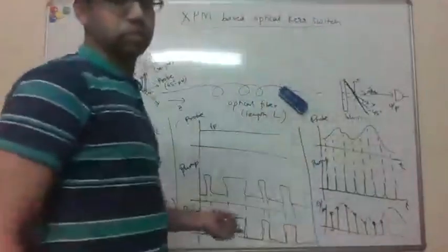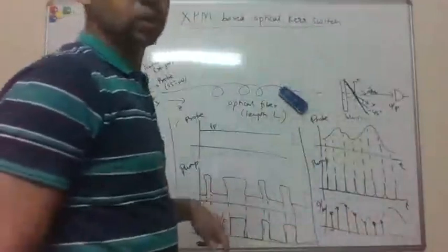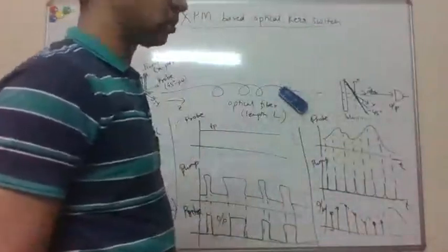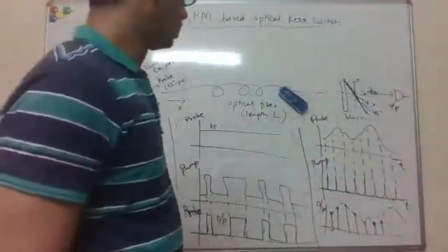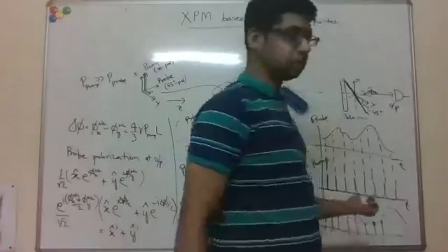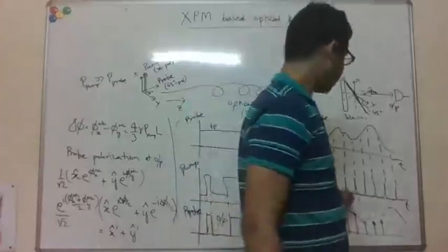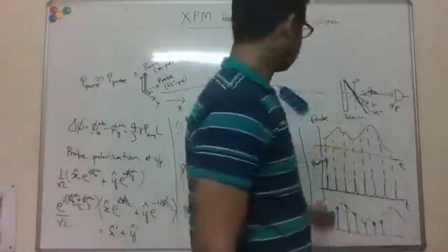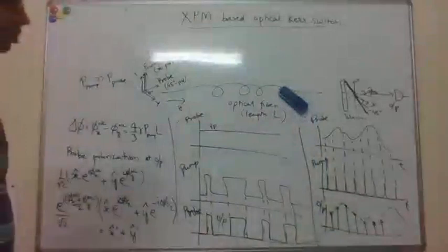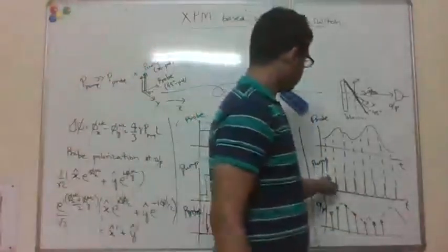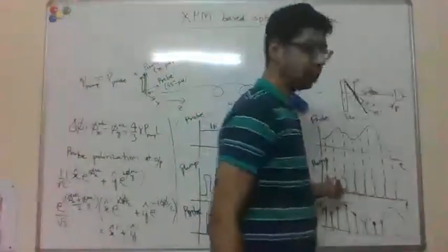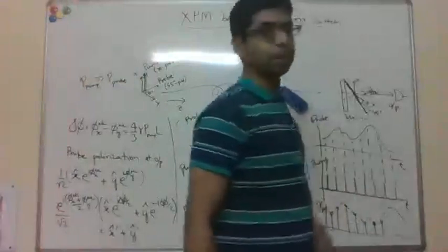And in the optical domain, the speeds can be much faster, right? In electronic sampling, you are restricted to 2 gigahertz rates. That's sort of the state of the art. But here you can get mode-locked lasers. Nowadays, people can make lasers which have repetition rates in hundreds of gigahertz, so you can sample much finer. Also, it's instantaneous sampling because the pulse width here is of the order of 100 femtoseconds or less.